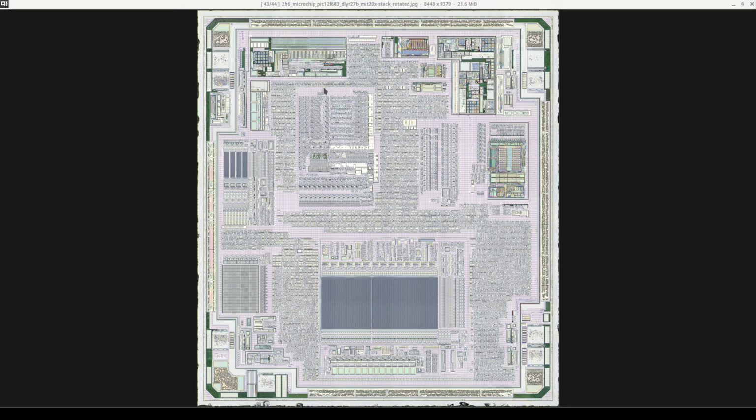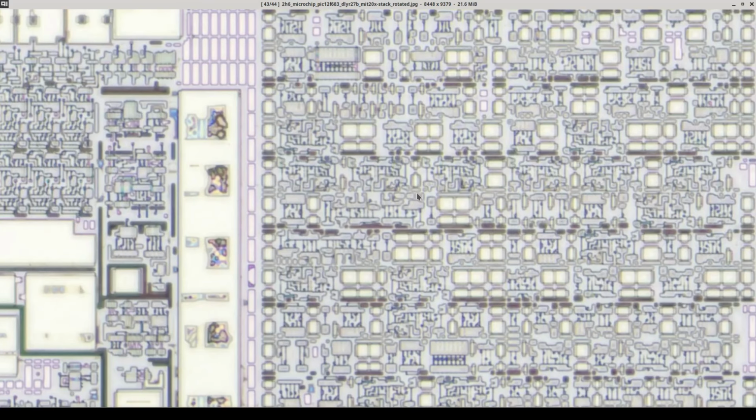And then a few other statistics that I haven't mentioned previously. The overall die size measured from corner of the seal ring to corner of the seal ring is 1.945 millimeters by 2.166, which comes out to 4.212 square millimeters. And the height of the standard cell rows is about 16 microns. The metal minimum pitch is about 1.77 microns, so this means we're looking at a 9-track high library. And also the basic 2-input gate is 5.88 microns wide, which comes out to 94.49 square microns.